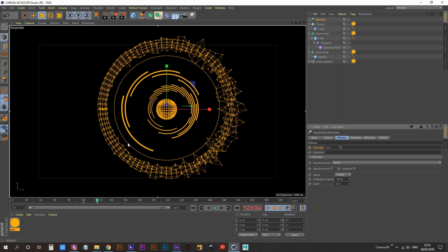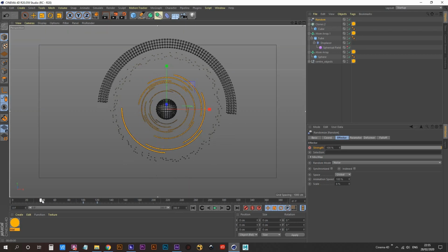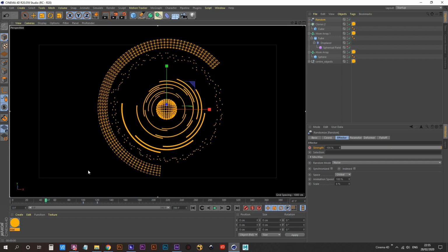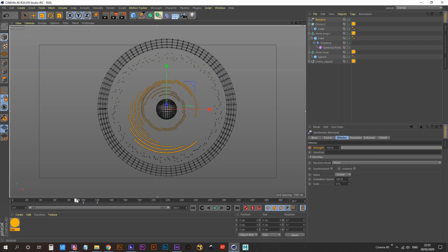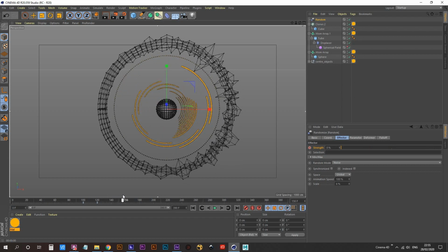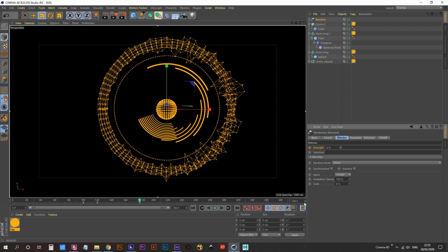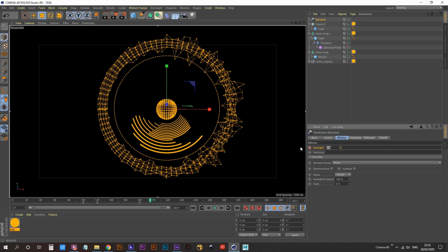Now you can see that that's creating a straight line here. So all of our cubes are in line. So now our animation is going to kick off. Our cubes here are all moving around randomly, and then suddenly they're just going to go zoom, and they're a straight line. They're going to remain straight until about frame 180. We're going to set another keyframe. We're going to go forward 15 frames and we're going to set it back to 100 and add a keyframe.